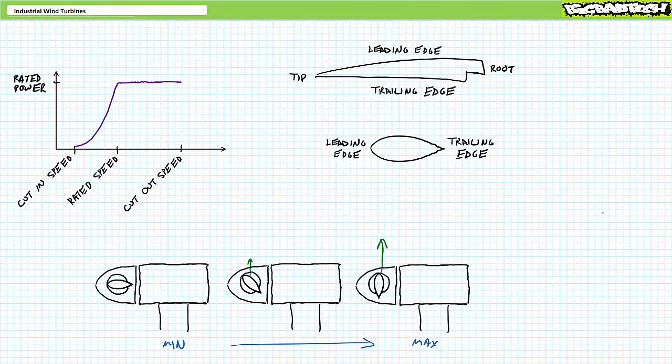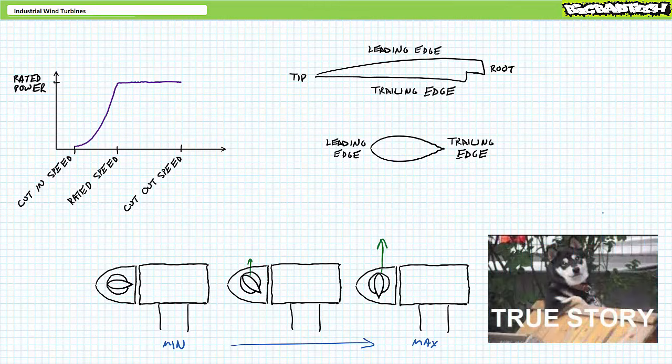Blades are meant to be mounted as a matched set of 3, and any imbalance between them is offset with a shot box mounted inside the blade at strategic locations that ensures all 3 blades weigh the same. You might ask, what happens when a shot box errantly opens during operation? Well, the shot spills out, the hub becomes imbalanced, and you get to get on your back on a skateboard and slide down the inside of the blade and test how claustrophobic you really are as you clean up the mess and restore balance. Again, ask me how I know.